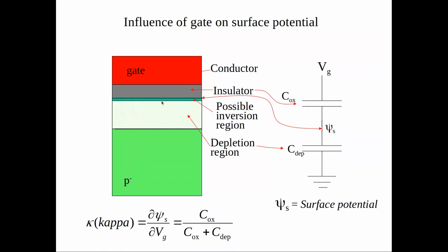Well, VG is the top. Sorry, VG is the polysilicon, it's the conductor, and Phi S is the semiconductor, below the Cox. So there are two different materials, and you can have positive charge on one and negative charge on the other. Okay. Yeah, because there is this insulator in between.